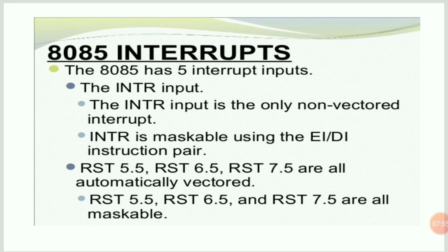The INTR input is the only non-vectored interrupt. INTR is maskable using the enable interrupt, disable interrupt instruction pair. RST 5.5, RST 6.5, RST 7.5 are all automatically vectored. RST 5.5, RST 6.5 and RST 7.5 are all maskable.